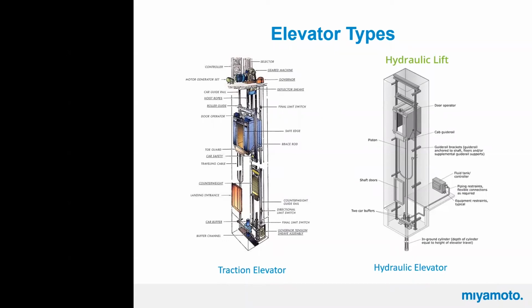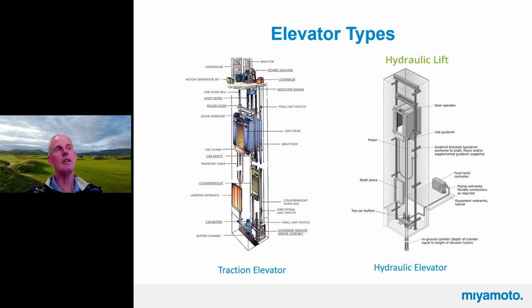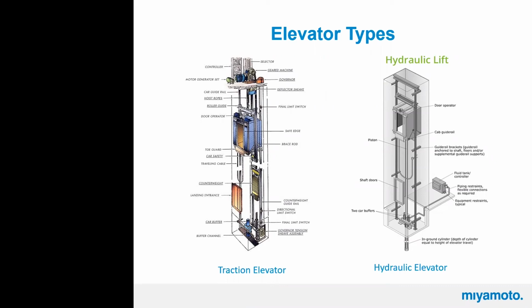So what would be your recommendation for design of those rooms while we wait for the actual machine load, like a pound per square foot that you suggest we use? Oh, I mean, it could be 300 to 500 pounds per square foot if you're converting it to a uniform load. Okay. I'm trying to think of the ones I've done in concrete buildings. I think we've started with like a 10-inch slab or something like that. They don't span very far, but you want them to be very stiff. Yep. Okay.